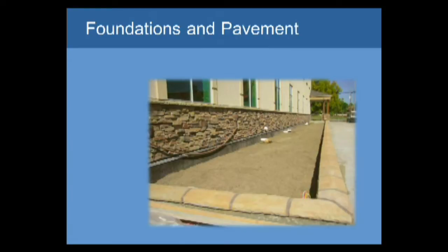Often I get this question: gee, can you really put a bioretention facility next to the foundation? The answer is yes, you can if your foundation engineer says that you can. And some foundation engineers will, in certain circumstances, say that you can. I'm not a foundation engineer, so I really can't say why they don't, but this is really just for folks who are in the business of trying to get these things in the right places, that it can be done. Often it means moving to a heavier foundation, substituting a mat foundation for footings, whatever it is, but these guys can do this.